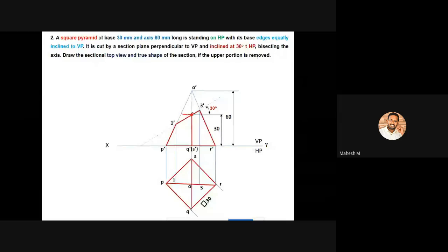You have to project the cutting point exactly at the axis up to slant edge. Then you have to project this particular point. So now you got another one more cutting point. So this one, you have to project this point up to the center line. That means the horizontal line of O2P.